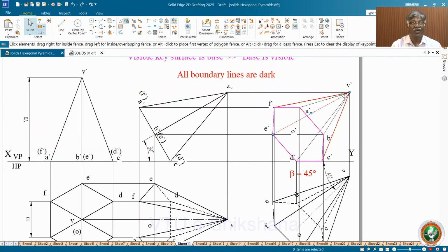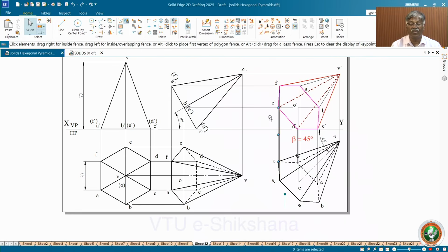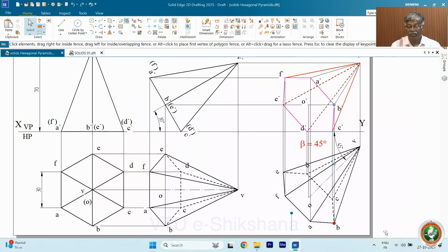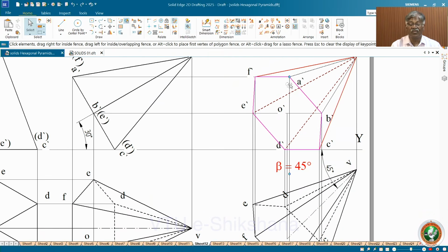that is here A to V is visible, B to V is visible. Okay, so you darken those two, or you can also prefer visible surface, invisible line. Yes, you can do. See, visible surface, invisible line. I have done that job. Next comes these two lines. What about these two lines? AV and BV, they are definitely visible because of bends. This AF is visible, AB is visible, definitely one more line joining, that is also visible.